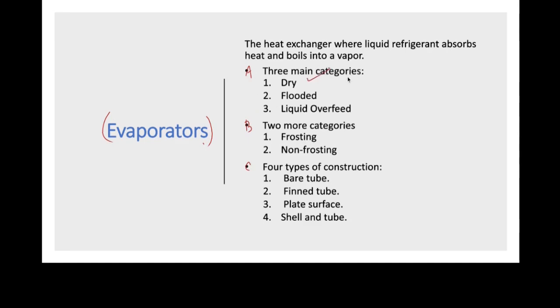It does have liquid in it for sure, but the amount of liquid varies with the load, and a certain portion of the heat transfer surface then is not going to be exposed to liquid. The flooded evaporator does a little bit of a better job because it maintains the heat transfer surfaces with boiling liquid all the time. And we do know that the heat transfer to gas is lousy, but the heat transfer to liquid, especially the latent heat of evaporation of the liquid, is really, really good.